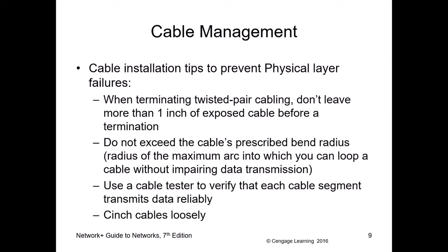It's called near end crosstalk, N-E-X-T. Near, like next. That's what it's called. And the other one is far end crosstalk. If you unwind the cable before you terminate it, if you unwind it too much, so you want to try to unwind it only as much as you need.